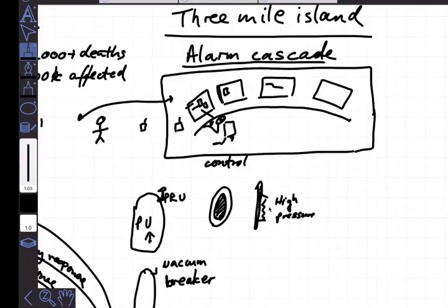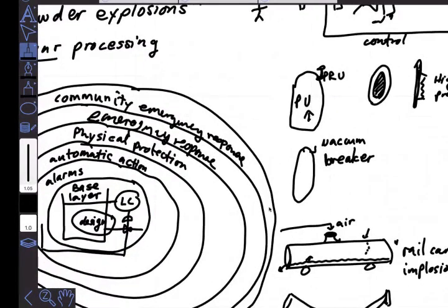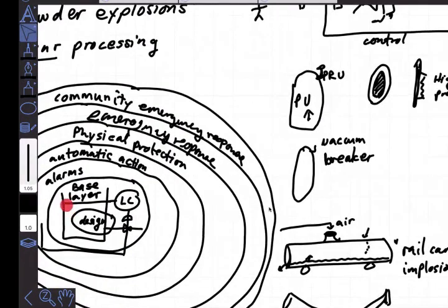So if you think that an alarm should give the operator time to react in a way that will make bad things not happen, let's talk that through. Let's say we want to put in a level alarm. We've got a tank here. Normally the level controller is working fine. We want to warn an operator of a condition where the level is dangerously high.